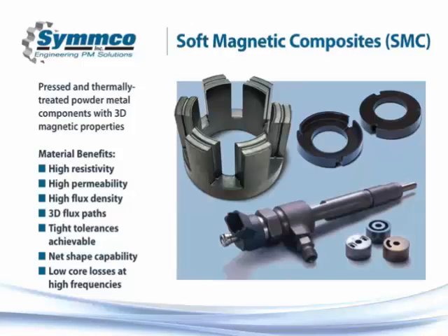But the great thing about that material is it is a 3D flux path material. So all of the parts that you see on there, the larger stator type parts, were all created from powder metal. The largest one we're making now is about 3.5 inch diameter, with some very small parts also. So it lends itself very nicely to the entire PM process.